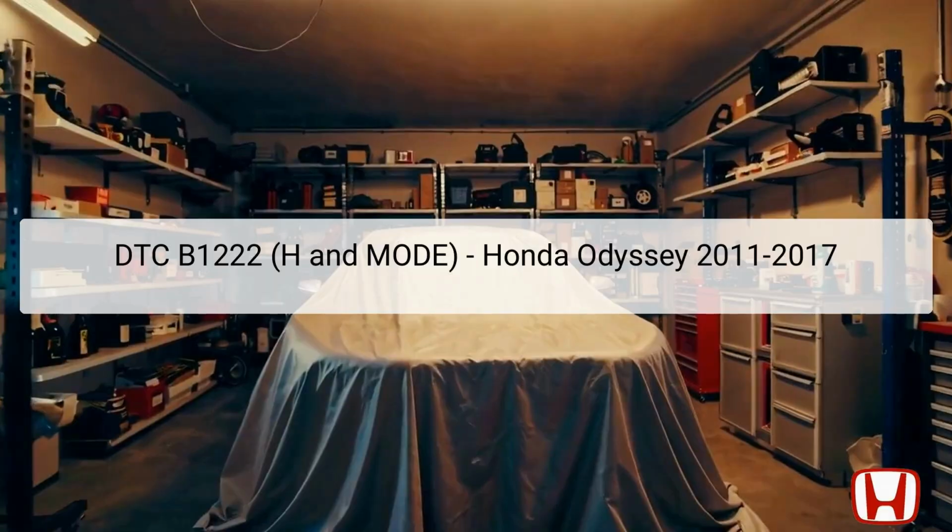The DTC B1222, also known as the H and mode indicator, appears when there is a short in the rear mode control motor circuit of a Honda Odyssey model from 2011 to 2017. This diagnostic trouble code indicates an issue with the climate control system, specifically related to the operation of the rear mode control motor.